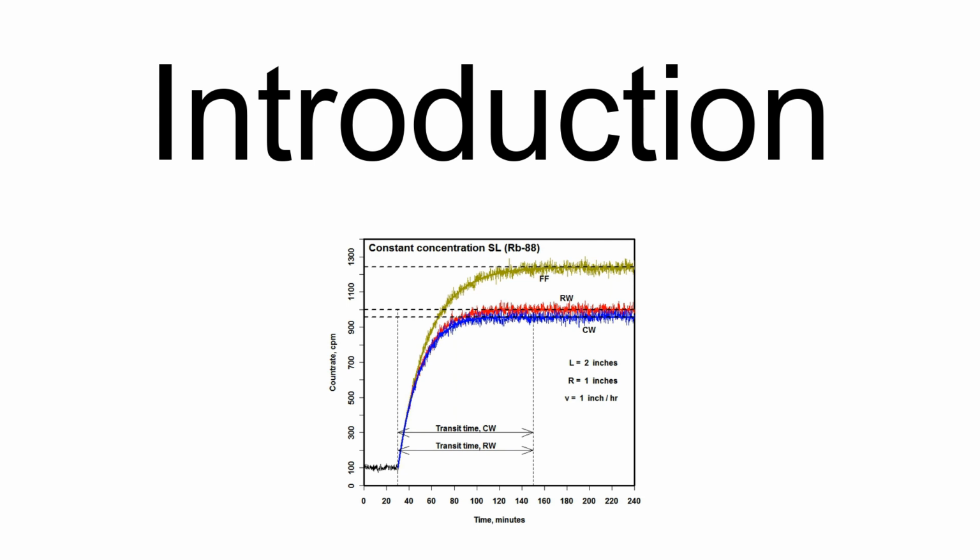CPAMs use a pump to draw air through a filter medium to collect airborne particulate matter that carries very small particles of radioactive material. The air itself is not radioactive. The particulate radioactive material might be natural, example radon-decay products, progeny, example 212Pb, or man-made, usually fission or activation products, example 137Cs, or a combination of both.